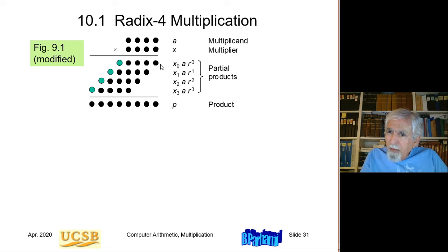With that one exception, of course, binary, we already know it requires the same width partial product as the number a. A decimal, radix 4, requires this extra digit. There is one radix, with some particular digit set, that does not require these extra digits. It's in fact an end of chapter problem. I'll let you figure that out.